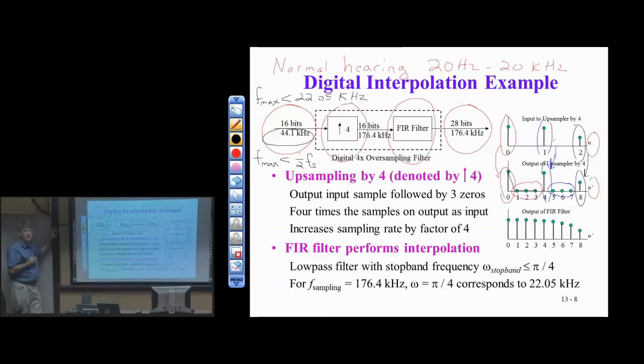No, you're good. Okay. So we want to get rid of those replicas at high frequencies, and we do this by using a good low pass filter. There are many possible FIR filters. It could even be IIR if you wanted to. It doesn't have to be FIR. For communication systems, we're going to use FIR filters. For image processing, we'd use FIR, but for other applications, it doesn't have to be FIR. Audio doesn't have to be FIR, for example.